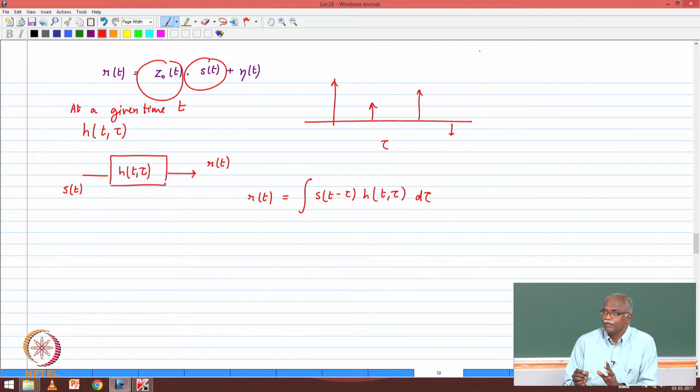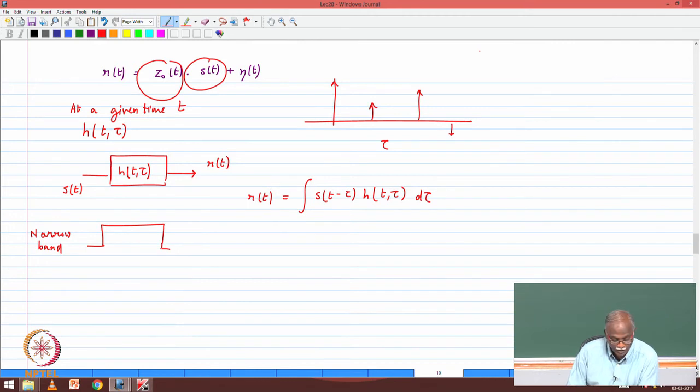So, therefore, how do I interpret the calculations? Narrowband signal. Remember, we talked about narrowband. How do I understand a narrowband signal? I transmit a pulse. I have to convolve with the channel, and because the pulse is very wide, my channel looks very narrow compared to the pulse. So, this is my channel response. This is S of t, the transmitted pulse. This is h of t comma tau. Again, the tau dimension is what we are looking at.